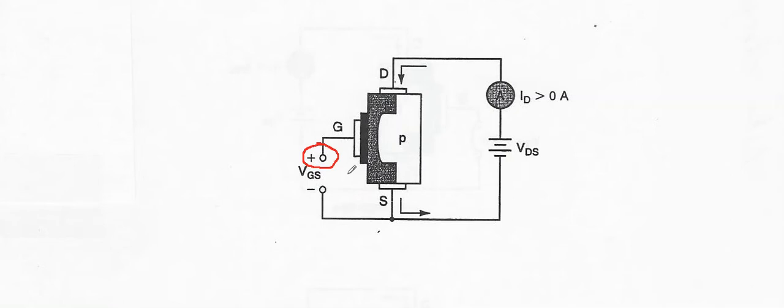For example, the N-channel E-MOSFET that we have here, you would apply a positive gate voltage to operate it. You would never do that to an N-channel JFET. You only use negative gate voltage with an N-channel JFET.